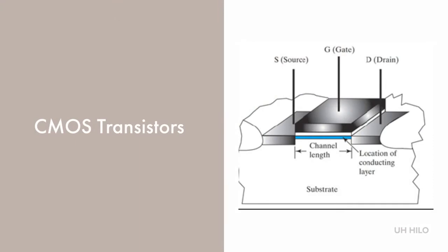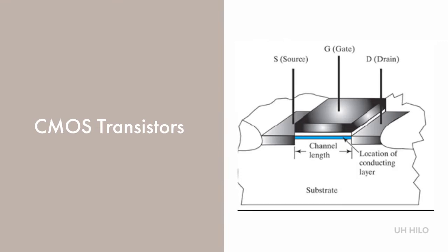Here we see a sketch of a transistor. For a sense of scale, we're looking at 1/1000th of a human hair. The substrate is the basic wafer material. The fabrication process modifies the substrate to be highly conductive in the source and drain regions. The conductive polysilicon gate has been deposited on top of a very thin insulating layer of silicon dioxide. The resulting structure consists of 2 identical conductive regions, the source and the drain, with a gap in between that lies under the gate. This is referred to as the channel.